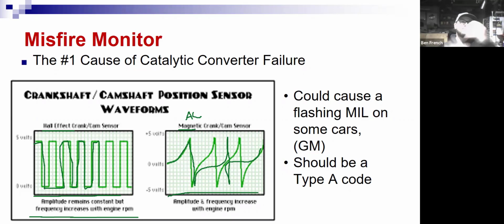So this is how stuff gets related, right? You could have a defective wheel speed sensor, which you'd think, hey, that shouldn't affect my engine at all. But that defective wheel speed sensor prevents Misfire Monitor from running. Maybe you also end up with a bad spark plug wire or something. It never sets a misfire code. The car is running poorly. The customer comes in for a lack of power. You find, hey, this thing's got a misfire. And well, why isn't it setting the misfire codes? Oh, because of that wheel speed sensor.